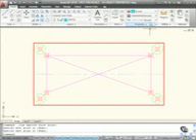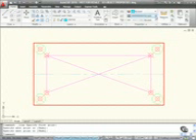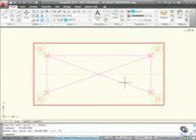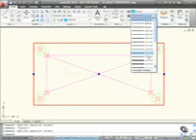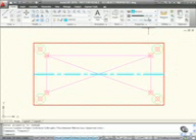But look, by layer for the line weight there, if I change that, that's the line type there. Line weight is just above. Easy mistake to make. Be careful which one you click on. I'll take that up to 0.35 as well. And you'll see there that even with the line weight showing at the moment, that's not adjusting. Can you see that? Because it's using a differing line type. So let's have a look at that in more detail. If I select that now, it's still on by layer. So I'll change that to 0.35, and as you can see, it's bold.